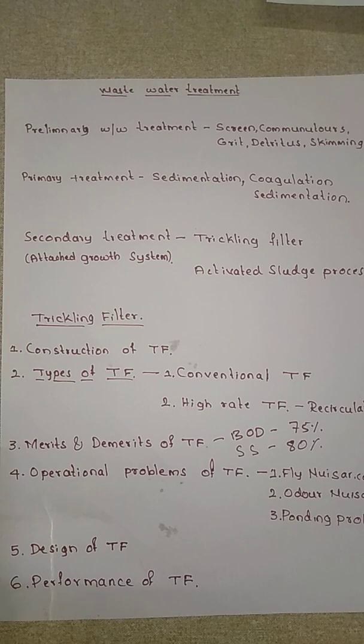The disadvantage is that the cost of construction of a filter is high, and these filters cannot treat raw sewage. Primary sedimentation is a must; before sedimentation we cannot go for a trickling filter. Okay, these are some of the disadvantages.